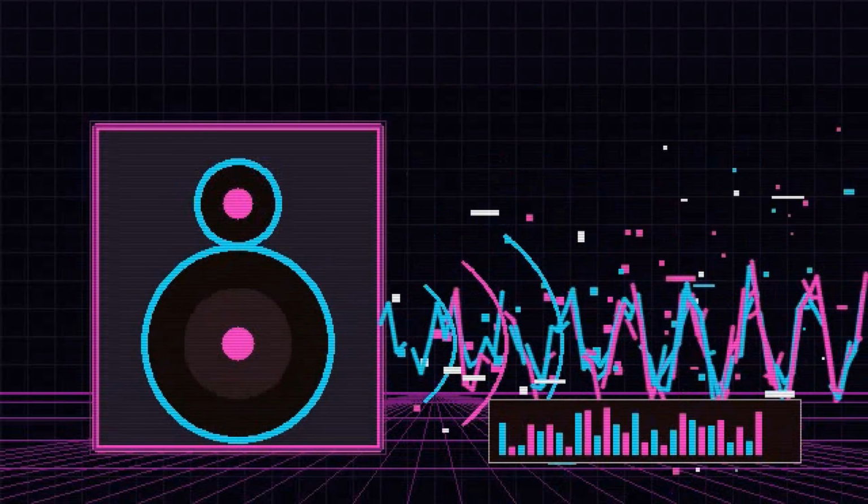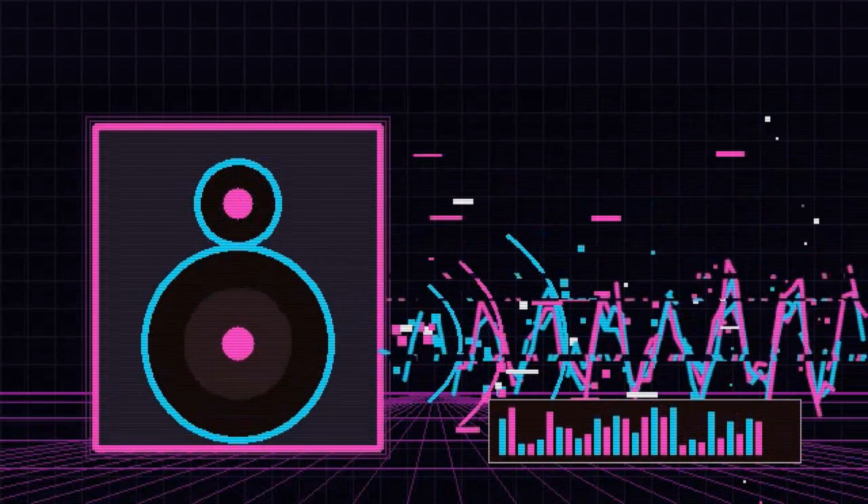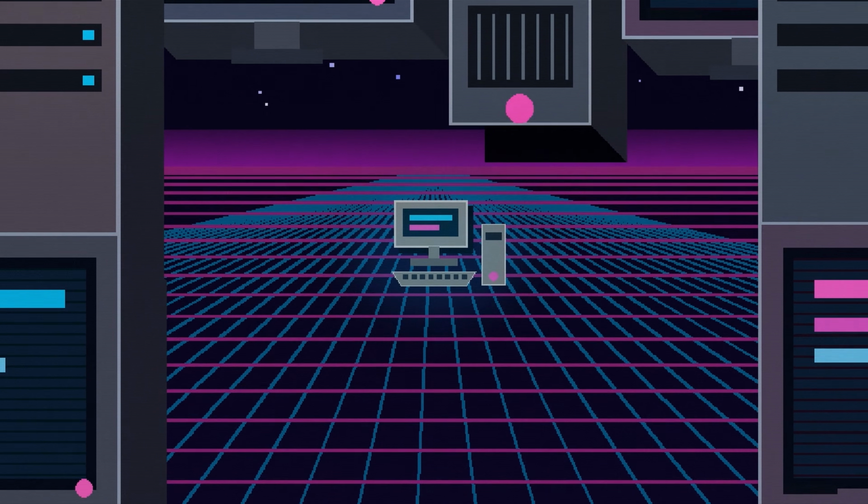My first version used a sample rate of 11 kHz, and it sounded terrible. There was a regular interruption roughly once every second. At first, I thought the audio timing was simply inaccurate, but the real problem was the Pi Zero. The problem was waking up more than 11,000 times every second to output audio. On a modern computer, that would be trivial, but on a single-core Pi Zero, the output loop was using so much processing time that Spotify could not decode the incoming stream quickly enough. The buffer would gradually empty, and every time it ran out of data, the audio clicked.